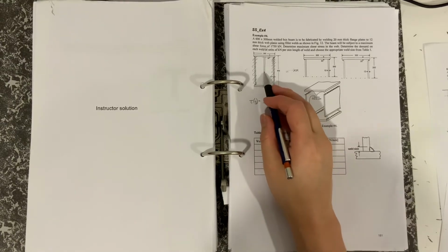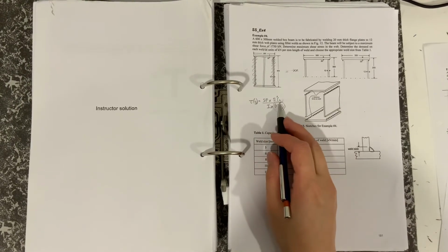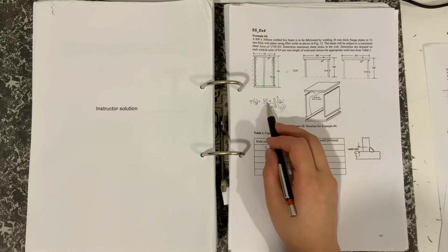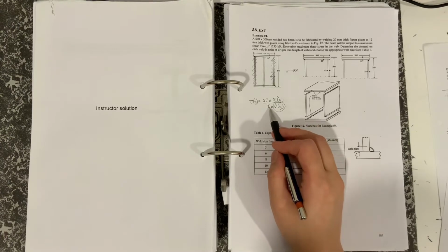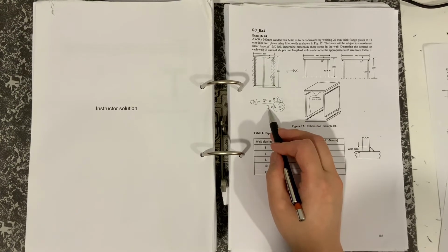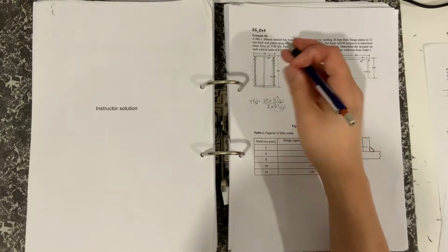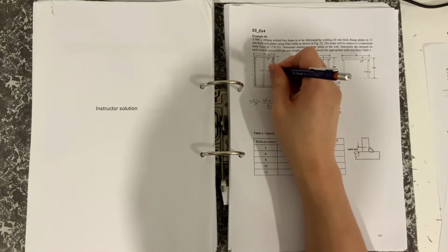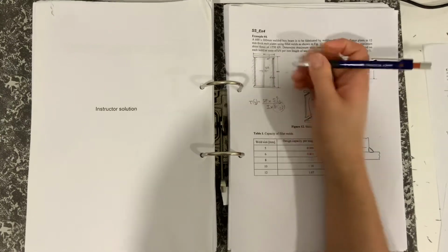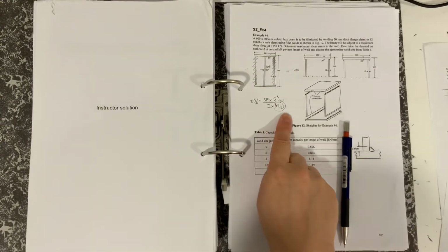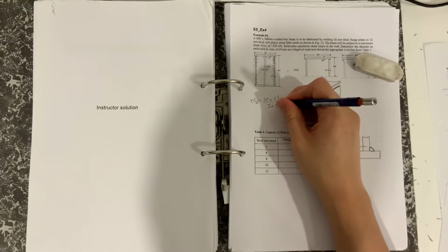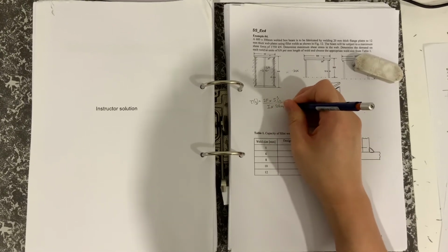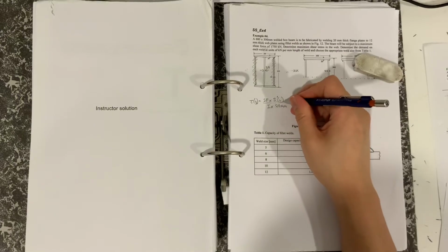I hope you can see that no part of this equation would change. The shear force is still the same, the S dash wouldn't change, and the I wouldn't change. You can immediately see that the breadth at the center is going to be 24. So if there's any confusion with the use of this equation, it should be obvious that when you work out the shear stress, b should be 24.